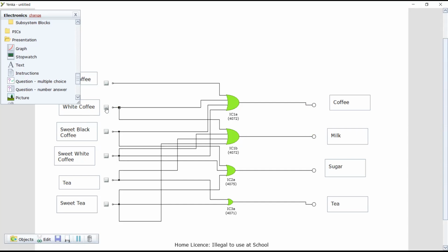So in this question, you're being asked to do two more of these. I would say when I press the sweet tea button, the milk output, the sugar output, and the tea output are switched on. And of course, they are here as well. To improve this into the sort of answer that you'd have in the TMA, you'd describe all the possible tests you could have in the circuit. So in the TMA, you have a list of criteria the circuit's meant to make. You should say what buttons you're going to press, what you expect to happen, and then you should record what does happen. And in many cases, I'm sure it will be the case that it does, but if it doesn't meet what the test expected, that's an important piece of information to record in your answer.